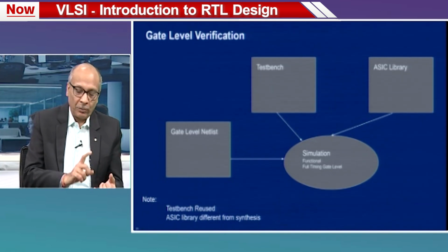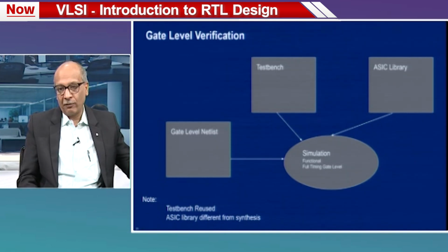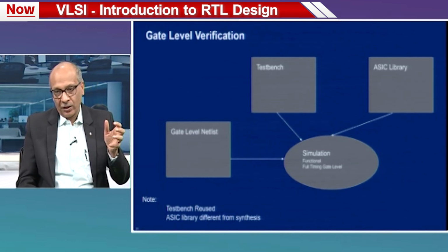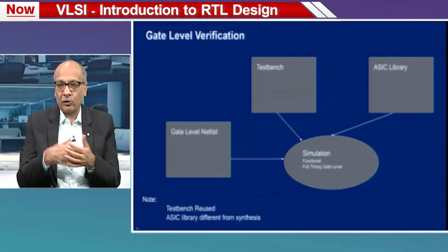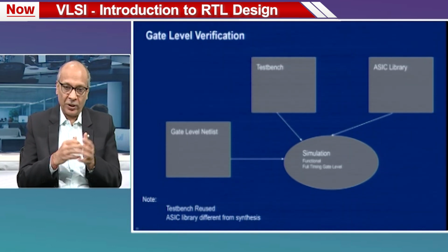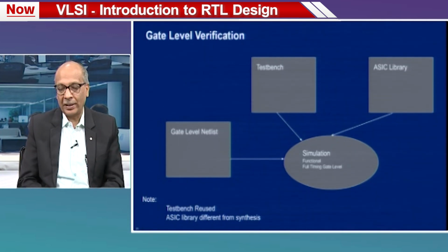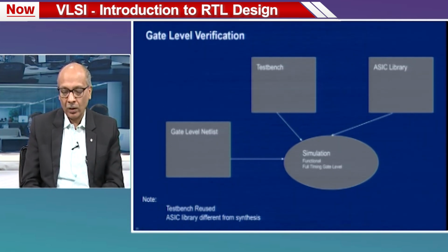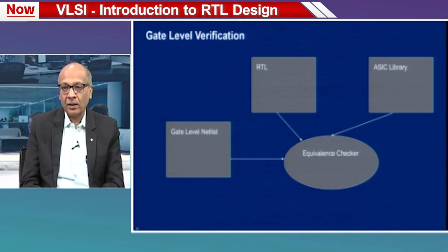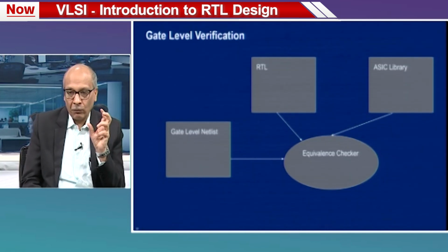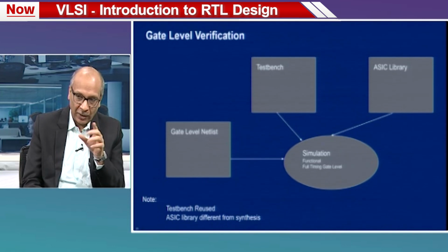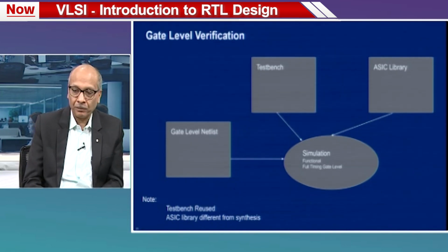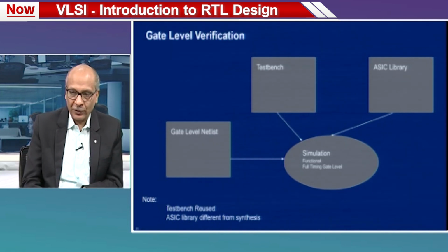So, when we are doing simulation, we did simulation at RTL level, we did synthesis. Now, we are doing simulation at gate level, first to check functional correctness, and then also to do full timing gate level simulation to check that the timing is also met properly. Lately, that full timing gate level simulation is not that popular, and we will see that in a slight while. But let us look at functional verification.